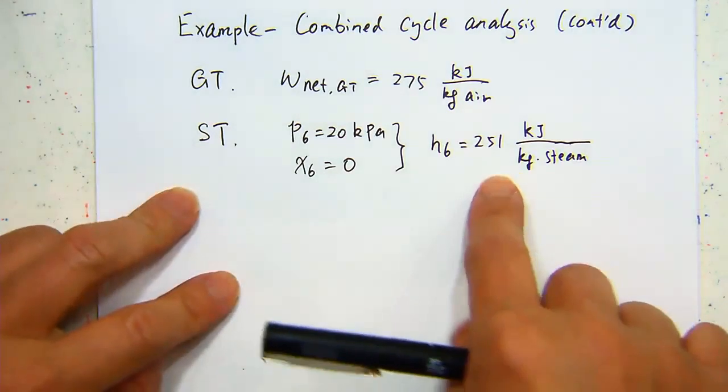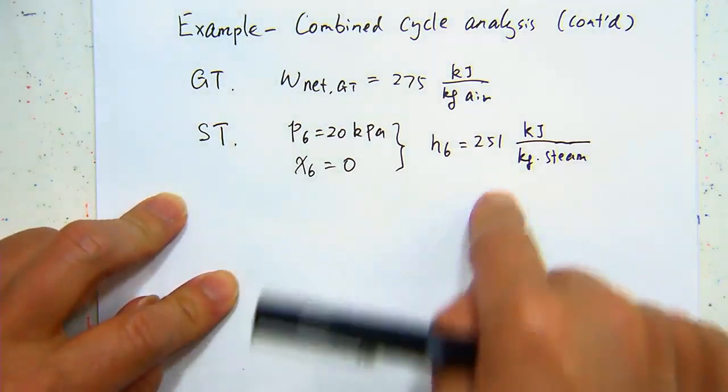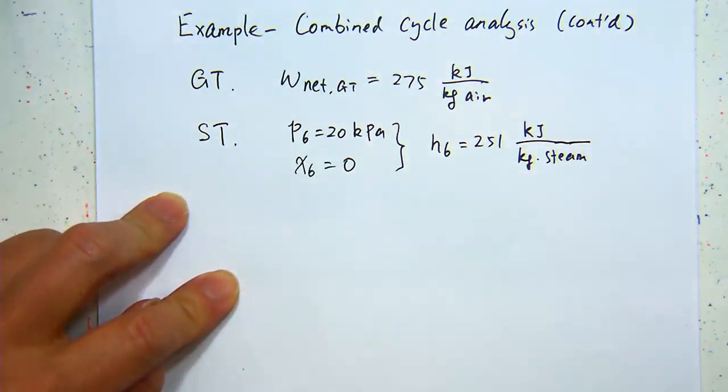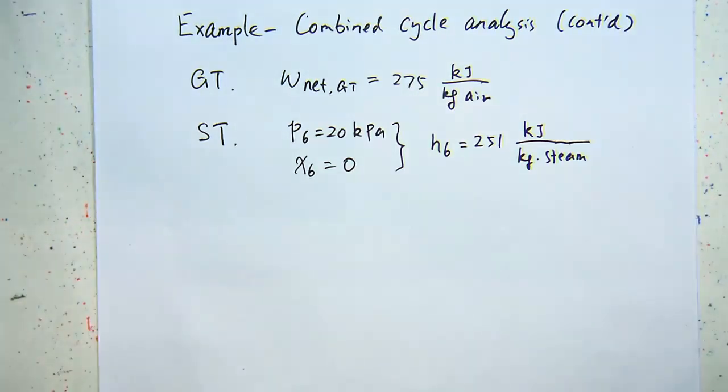So you go to, as mentioned, the different tables. For water, in particular, you have 3 tables. You have the saturation table, dealing with all the properties underneath the saturation dome, including the dome. You have the superheated table, which is on the right-hand side, and the compressed liquid table, which is on the left-hand side.